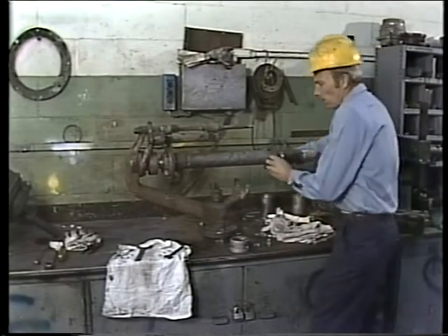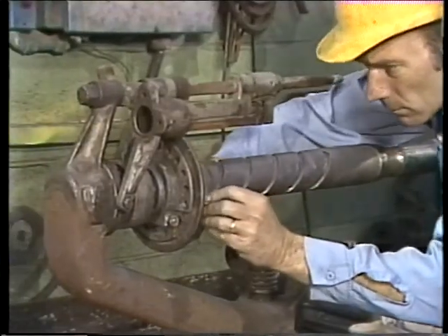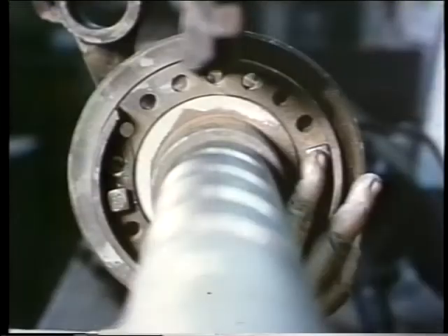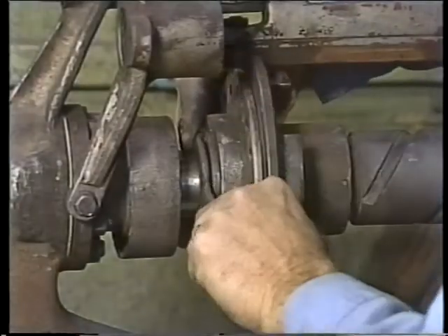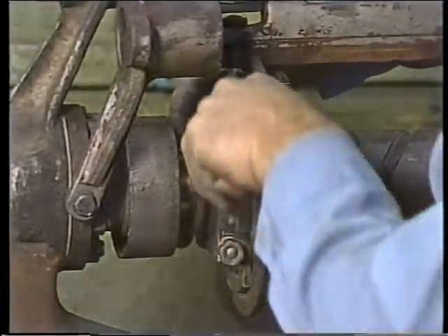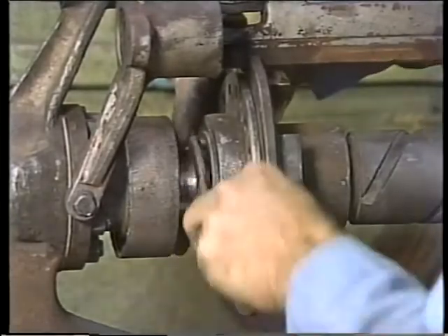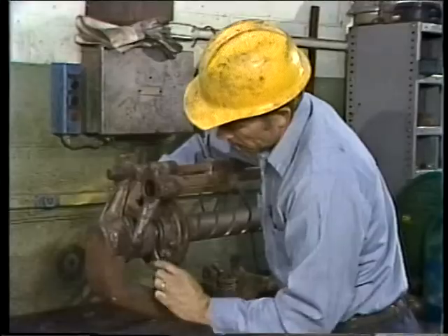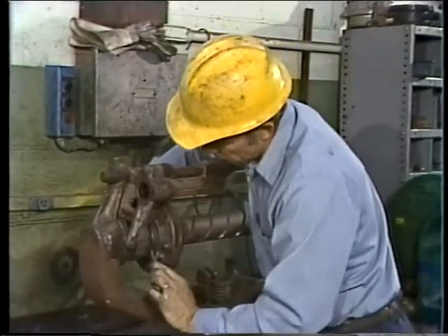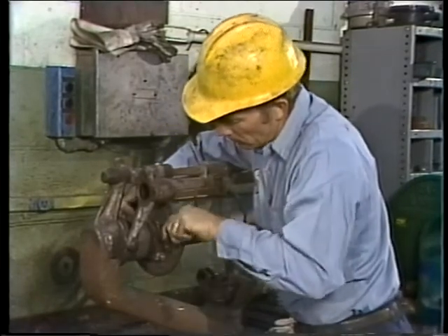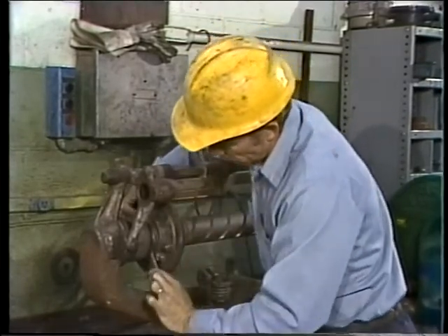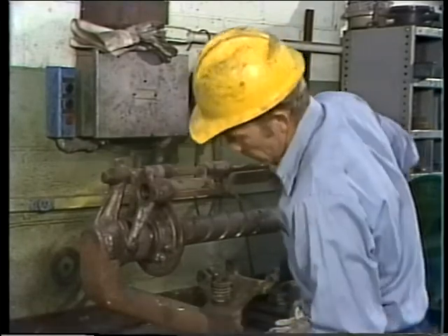The cam is next, held on by 2 bolts with nuts and lock washers. He's got to be careful to index it the way it was fitted originally, or it might cause the soot blower to bind up. Then the gland follower is put into place. On the soot blower we're using for our example, a spanner wrench is used to tighten the gland follower. For now, it's just snugged down a little. He's going to have to slide the element in and out some, while some of the other parts are being reinstalled.